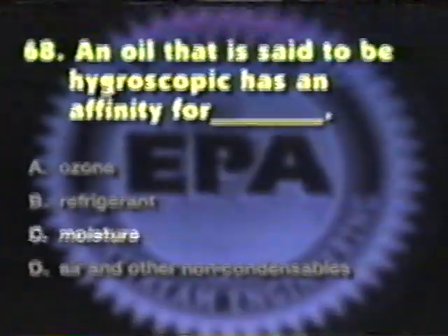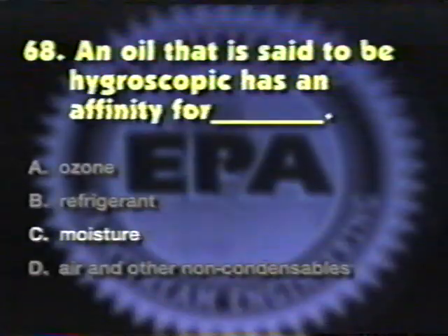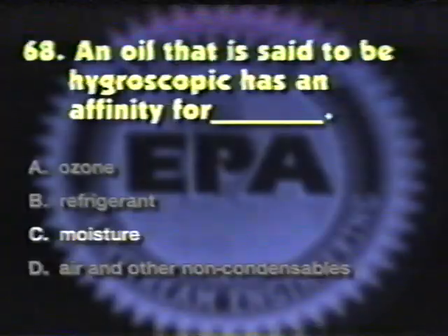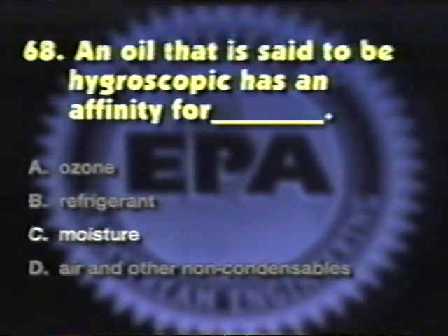The answer is C. Moisture. Hygroscopic means attraction to water, so hygroscopic oils are oils that readily absorb moisture. POE and PAG oils are hygroscopic.